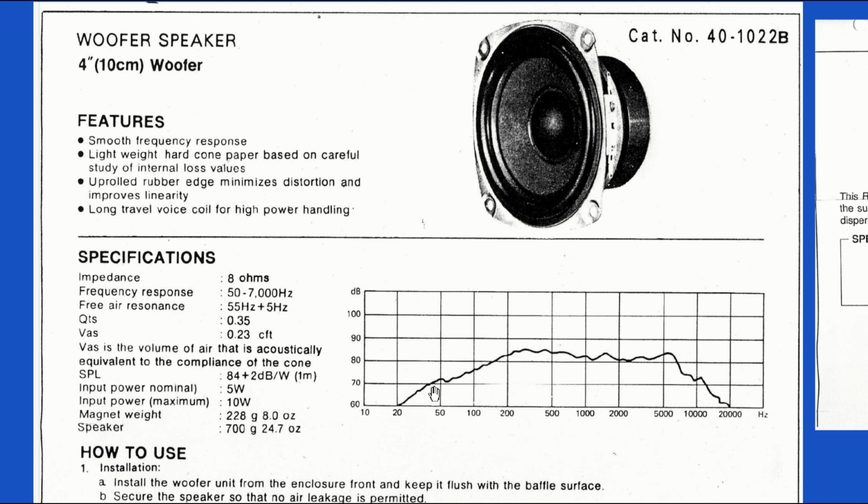It'll do some 50 hertz and some 20 hertz, but look, at 20 hertz, you're down 20 dB, 25 dB almost, from 85 down to 60. So that's pretty quiet compared to the mid-range of the speaker, which starts arguably around 150 or 200 hertz. And then we can see it goes up to at least 5 kilohertz or a little more, and we'll call this 7. So yeah, 7 kilohertz good, 50 hertz not so much.